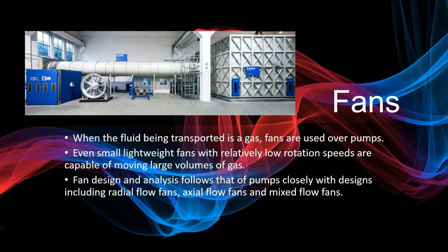Just like pumps, fan designs include radial flow fans, axial flow fans, as well as mixed flow fans, and their analysis is fairly similar to that of pumps, simply using different data terms such as pressure rise instead of head rise. Most fan analysis takes place under the incompressible assumption, or constant density. This is because the change in density for gas flowing through a fan system isn't normally enough to be considered impactful in the system.